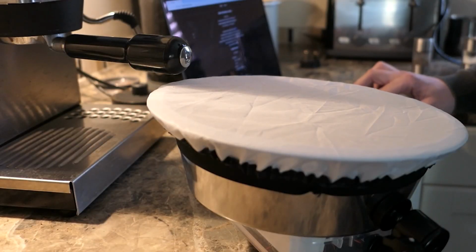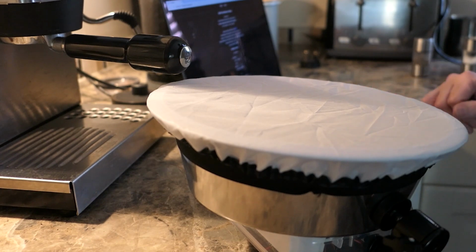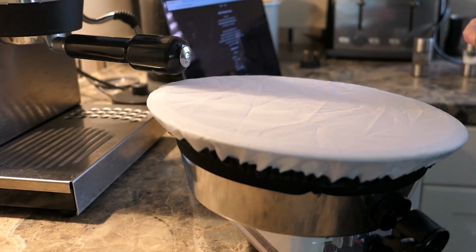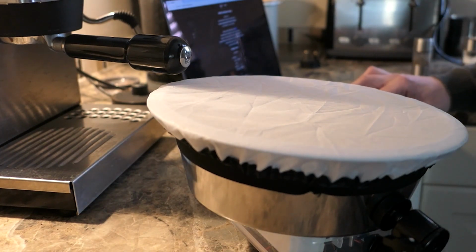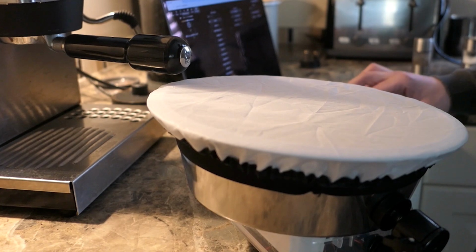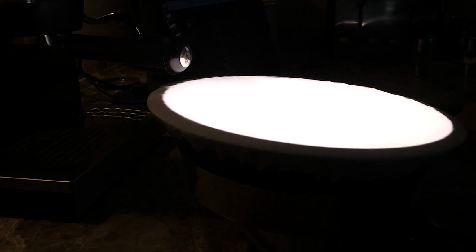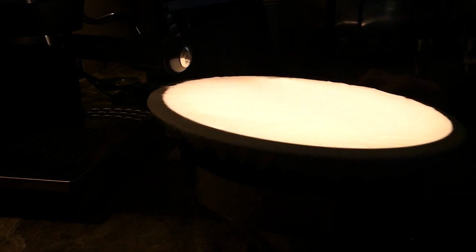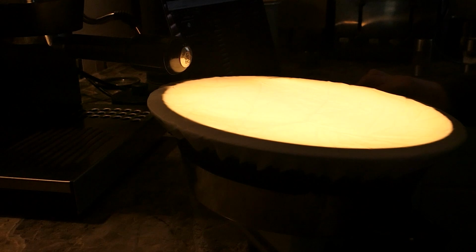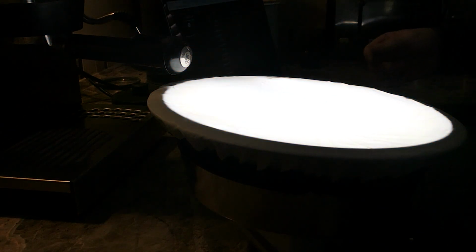Here I am back in my kitchen, and I'm configuring WLED remotely, using my Wi-Fi to connect to the ESP32. You can also see on the lamp that I've added sort of a diffuser cloth. This is something, again, I bought from Amazon. It does a great job of diffusing the lights so you don't see the individual LED strips. So I'm just setting up WLED to get the right output pins, and I've put it on PWM mode.